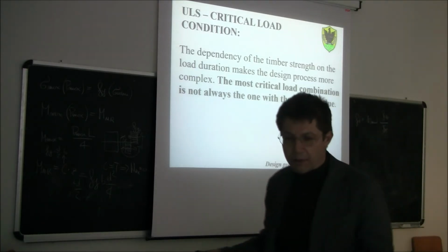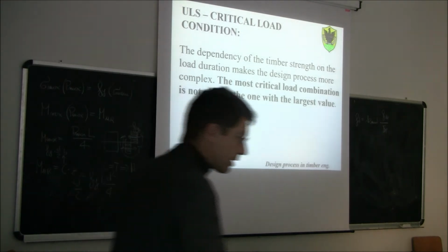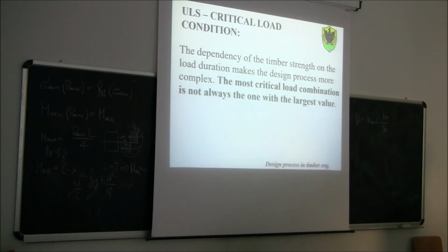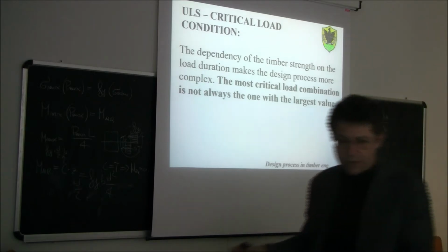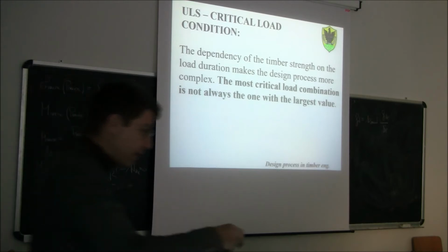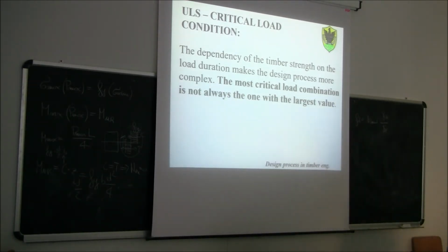If you remember well, when you studied the limit state design philosophy in the reinforced concrete design course that I gave some years ago, if you have different variable actions, you assess the different values. For example, you have three variable actions, you have to consider one variable action as the fundamental load, and the other two become combination actions.